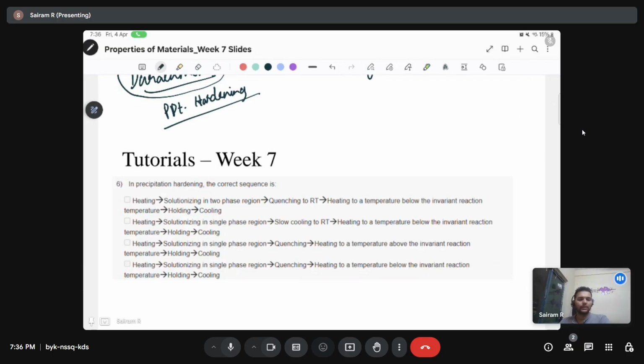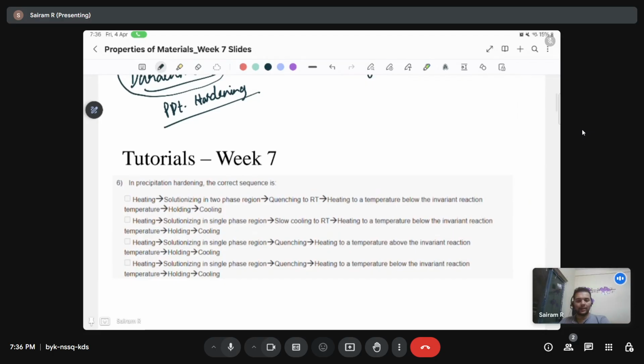The best way to do that, even during the initial solidification, is to take it to liquid temperature and then quench the system from there. If we are able to optimize the heating rates and cooling rates during the solidification process, we'll be able to form very fine precipitates, or precipitates of appropriate size, that give us the best hardness or strength conditions.